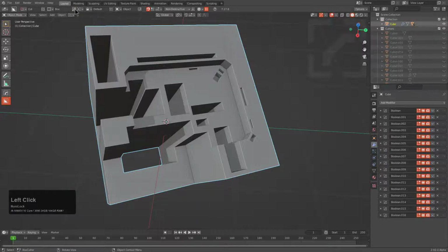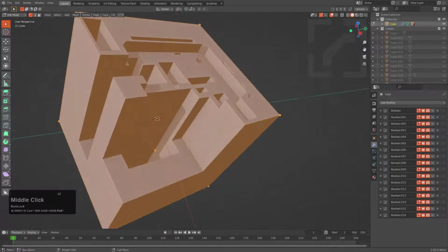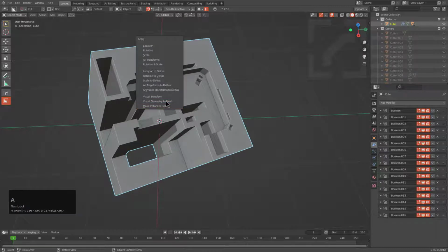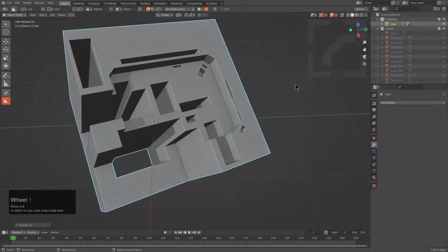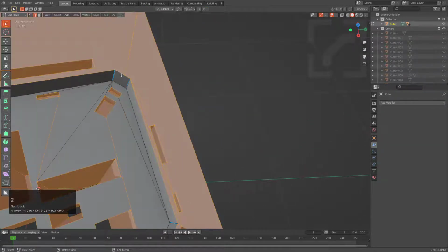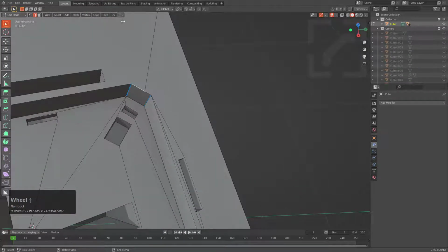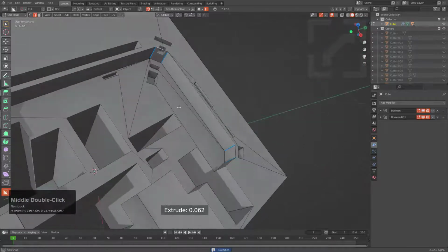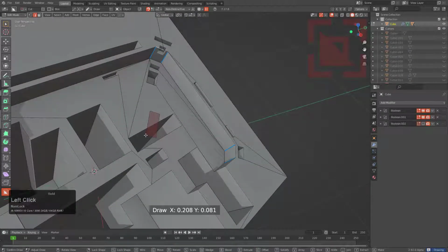Another way is that by going in edit mode, we can actually select edges and orient to those edges. So let's say that this mesh was real. So these modifiers are applied. Well, now I can go in edit mode, I can select this edge, and then if I perform a box cut, we're now oriented to the edge that's selected. And if you don't believe me, we'll select another edge and try to draw a cut, and we see that it's oriented differently. So this is another way that you're able to work if you have some geometry to get you started inside of BoxCutter.